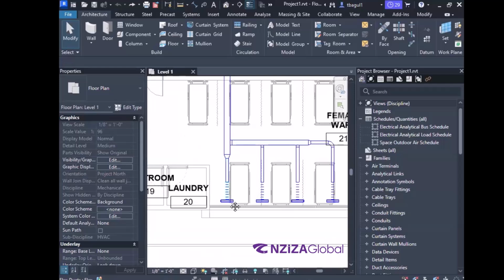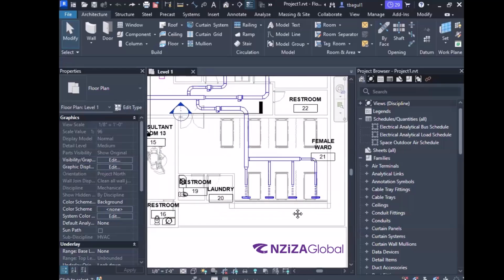So in this case, try not to have the diffusers right over their head. Making sense till now? Very common issue that happens in hospitals. If you have an office building or a manufacturing facility, it's fine. But over here, try not to exactly center the diffusers on their head so that the cold draft air doesn't hit their head and make them even more sick.